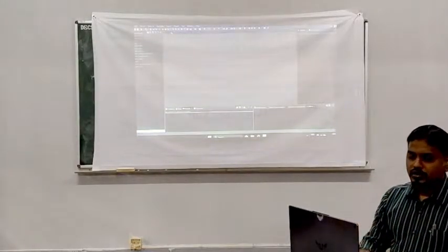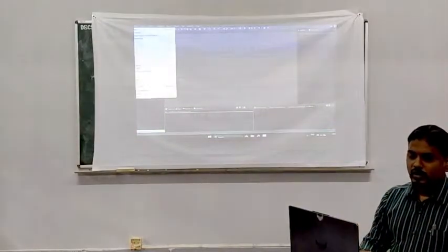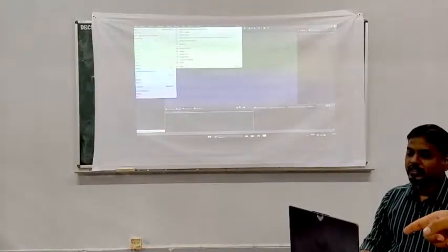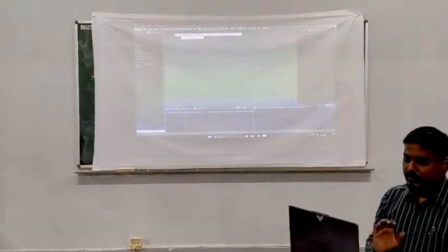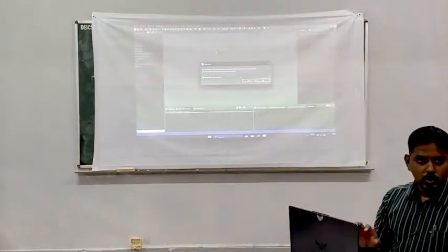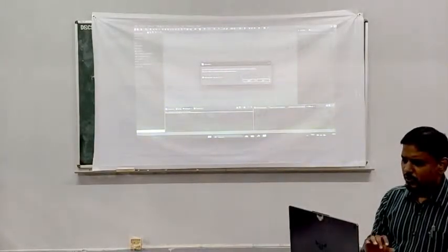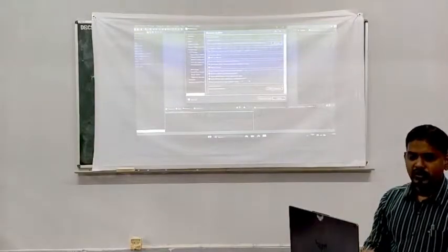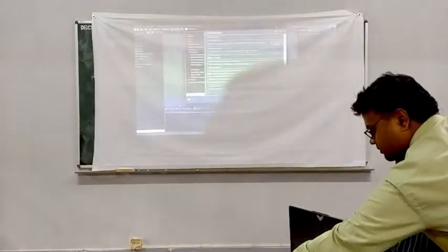Okay. So just go to File, click New. Okay, and here you can see the STM32 project. Please click that. It will show one question. Just click yes. You don't need to do anything. Okay, it will open this page. Maybe the first time you do it, it will ask you to do the firmware update. I think everyone has done this firmware update.